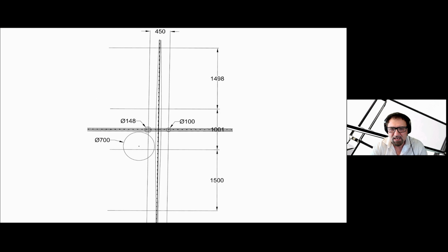In a very rough sketch, I'm giving you the layout of the starting point. To simplify the work, we will just use the taper for the widening, where we'll also reach the offset from the main line and arrive at a location about 220, 230 feet away from the actual intersection, where we will work on the two roundabout or rotary shape type of alignment.